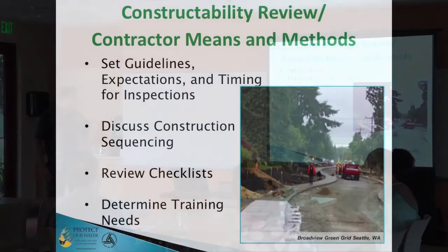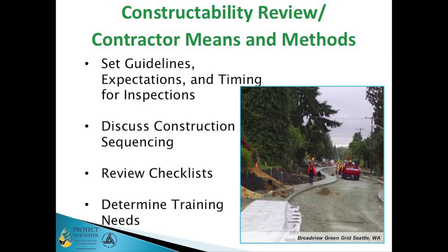I put constructability review and contractor means and methods here, and this really is a little bit out of order, but this is something important, particularly on a large complex project. I always try and work with clients to get the construction management team on board at least at the 90% design, to look at the plans and specs and make sure that what our designers are coming up with is something we can actually build in the field. Because our construction folks are the ones that know what actually happens on the ground. And they can add a lot of value to these projects sometimes.